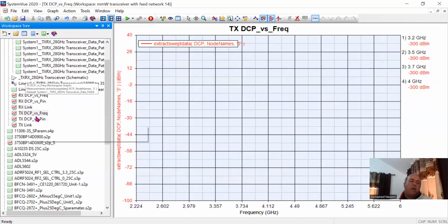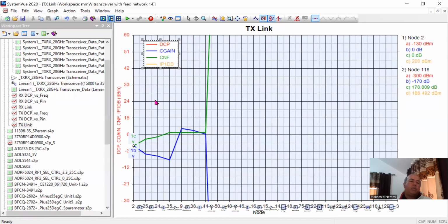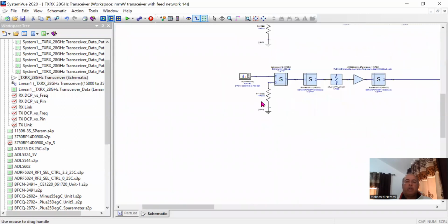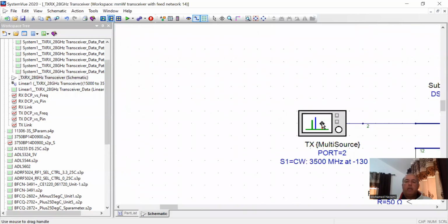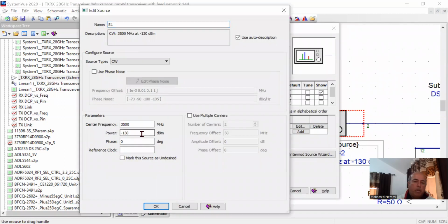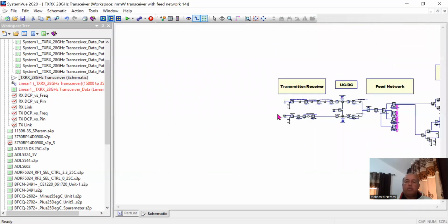Okay, so right now in the transmit section, I don't have anything in here, so it's all not done correctly. Because I killed the signal on the transmit, I'm going to go in right now and configure it so that I transmit. First thing, I'm going to put minus 13 dBm in here, instead of minus 130 dBm, which is basically muting the RF on the transmit section.